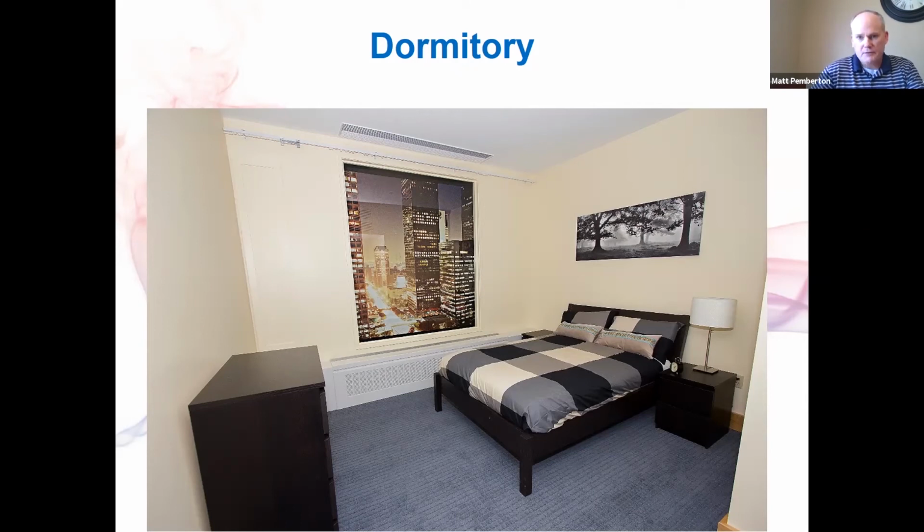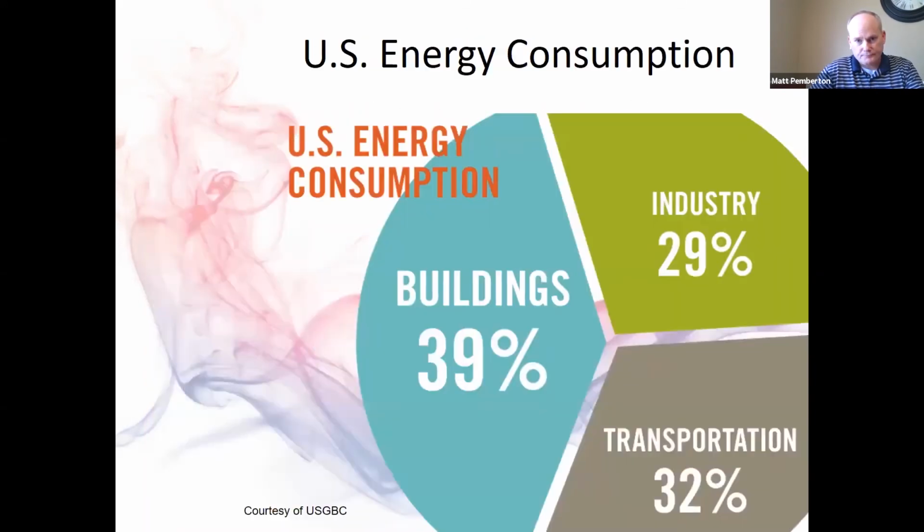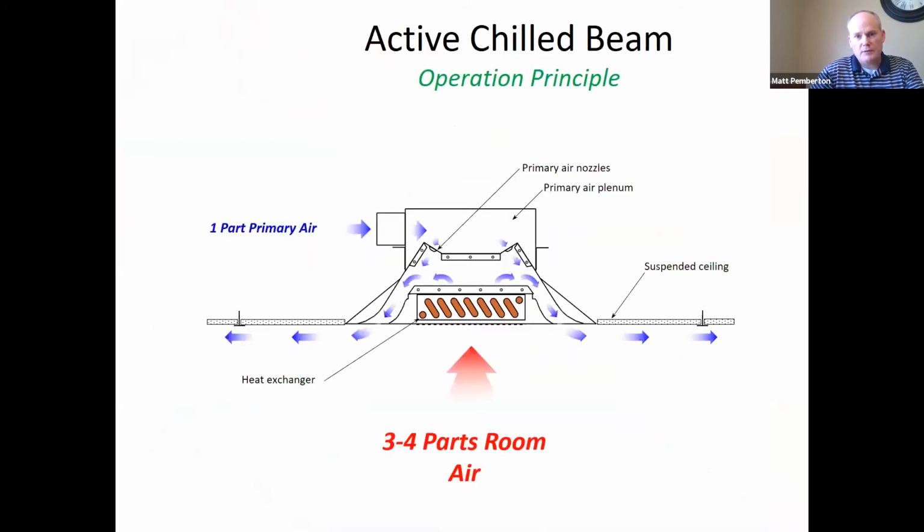And when we go to 4-pipe, the benefit there is you'll notice on this one picture, on the active chilled beam, it's showing you 2 rows of coil. There's a 2-row coil, 1 supply, 1 return connection, and there's 8 tubes in each row. So if we were doing cooling, we'd be using all 16 tubes for cooling. Then with the changeover system, we'd use all 16 tubes for heating. If we want to go 4-pipe, we'd take the same coil bundle of 16 tubes and we'd run a 12-tube cooling circuit and then a 4-tube heating circuit. So still equaling 16 tubes.